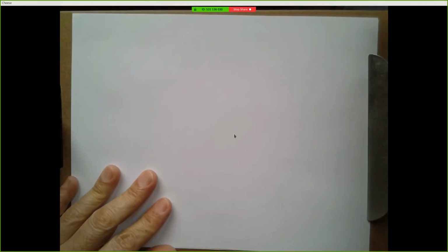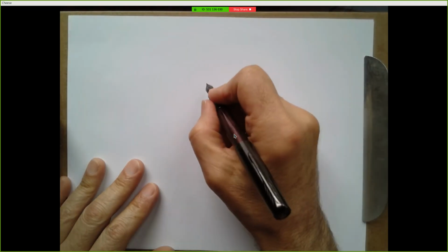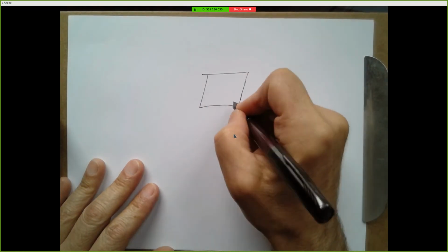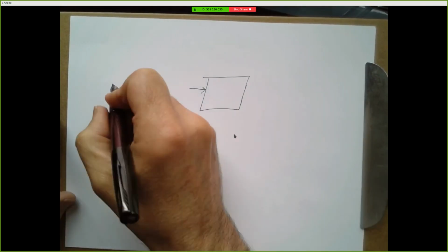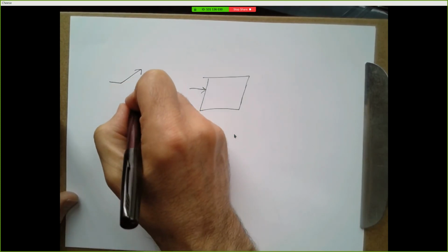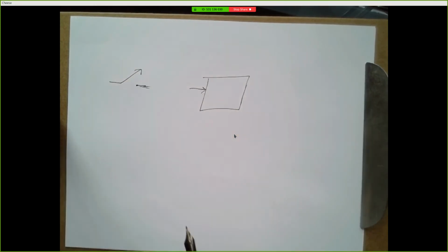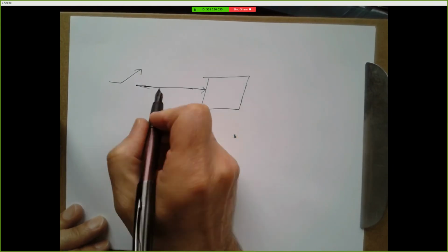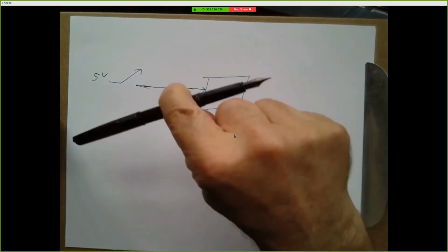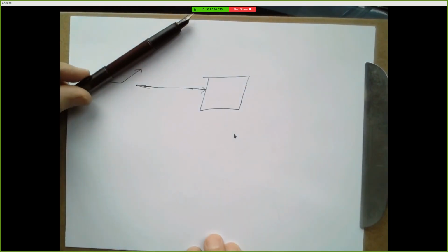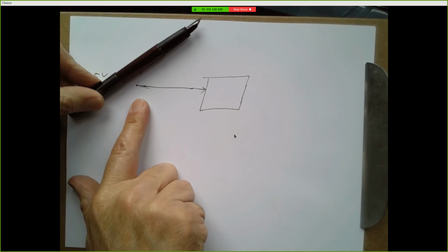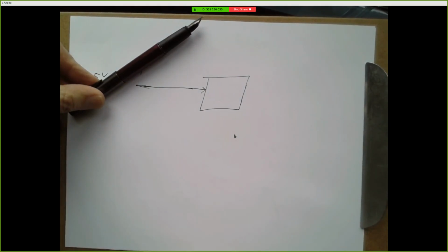Alright, the input side is a little more confusing, but if we do it like this, it will always work. Let's say we have a circuit and we want to feed in either 5 volts or 0 volts. Okay, the switches we have are typically something like this. We can make a connection or we can break a connection. And we might try to do something like this. And now, yeah, if we close this switch, we get 5 volts going into the input. But the problem is, if we open the switch, the input's not connected to anything. And that's not the same as getting a logic 0.